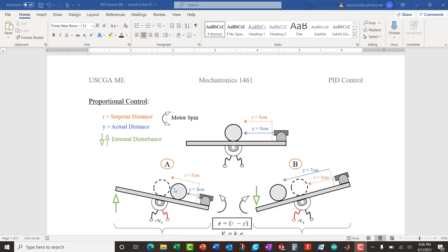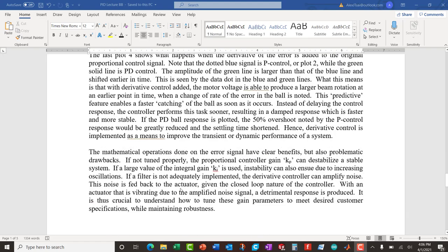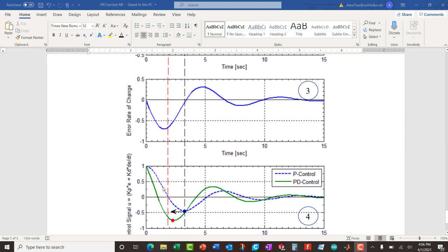And control theory tells you how. How do I capture this moving ball, that rate of change of the error, and use it in my signal? And what's the magical number? What is the D gain that I need for this to go back within, I don't know, half a second or maybe a quarter of a second? So the customer decides how fast the ball goes back. But the derivative control essentially captures the rate of change and acts upon that in an earlier moment in time, as opposed to the proportional controller, which would be later.